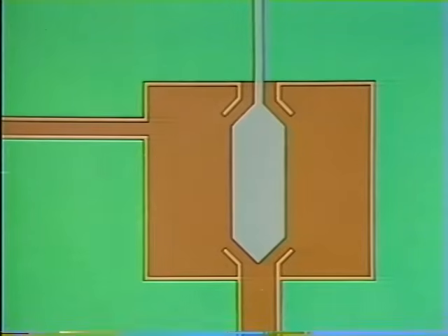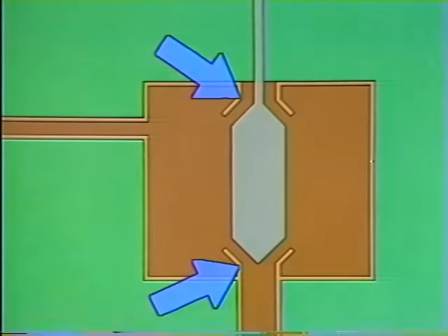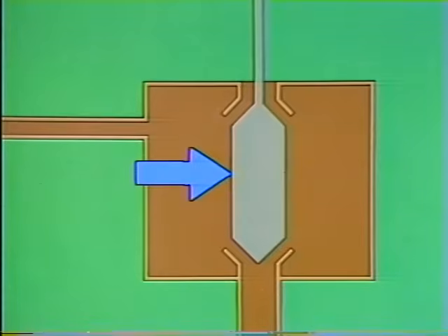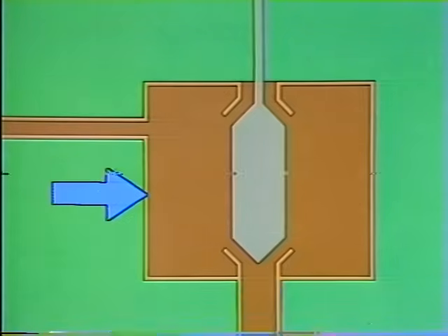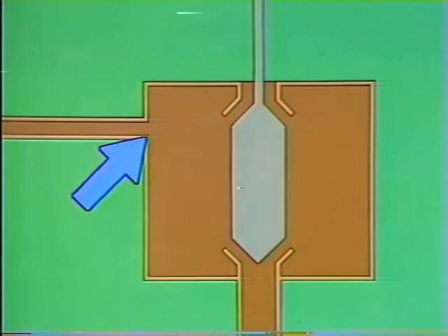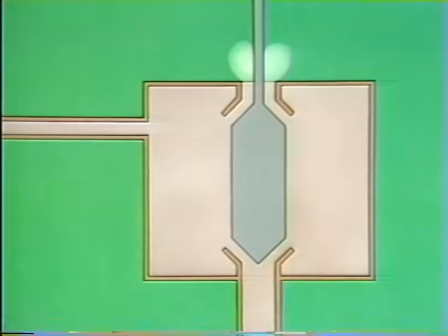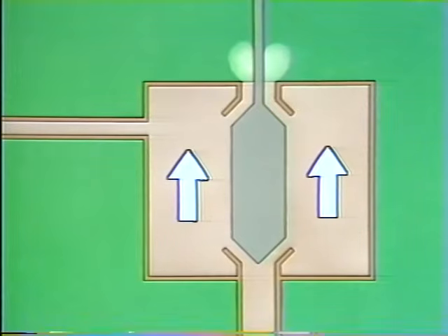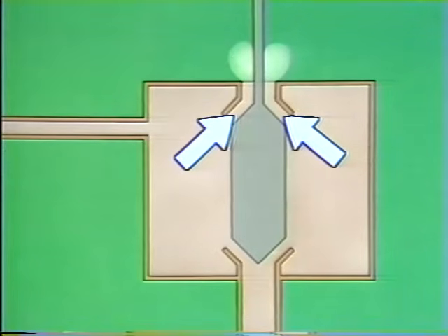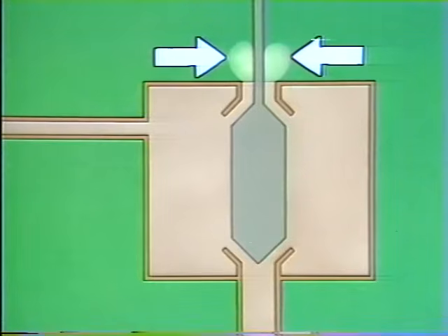The elements that are common to most pilot valves include two restrictions, a plug that can simultaneously vary the size of the two restrictions, an air supply, and a back pressure compartment with an output connection. Generally, the mechanism works like this. Instrument air flows in through this supply port, past the inlet plug restriction, into the back pressure compartment, around the exhaust plug restriction, and out the exhaust port.